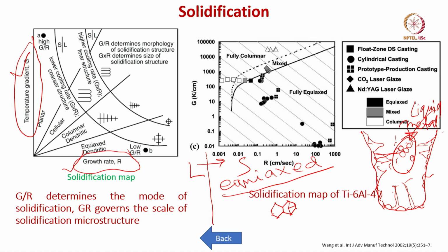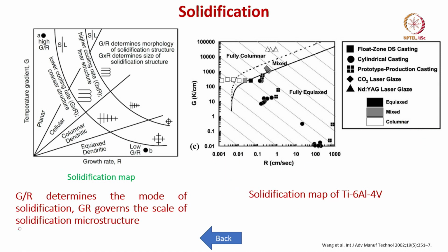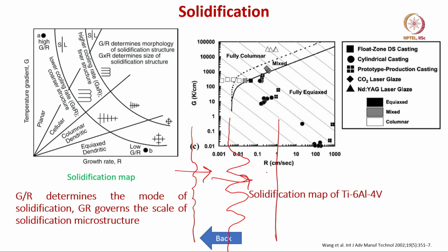This is called the planar solidification front. When this planar solidification front breaks down, it gives rise to some kind of undulation or perturbation in the structure. When it grows, this undulation also grows with time. It grows and becomes very unstable, and then it is broken, right. This actually gives rise to more or less a dendritic type of structure.